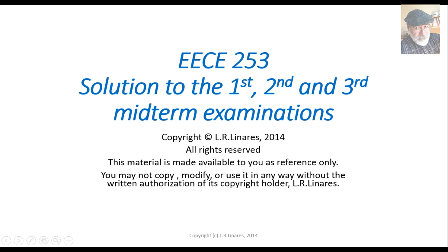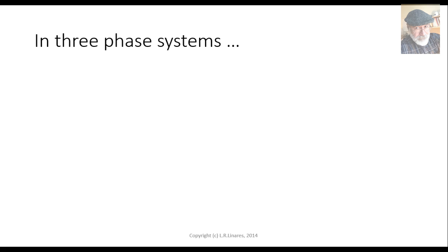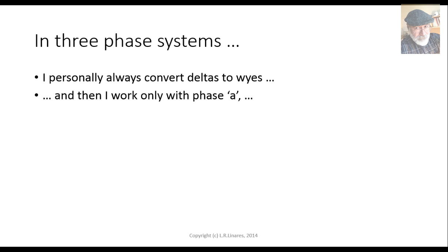This is the solution to the first three midterms. Before we begin, let's recap on a few basic concepts. In three-phase systems, personally, I always convert deltas to y's. That is a thing I do. And then I work only on the phase A of the three-phase system, the single-phase equivalent of the circuit.